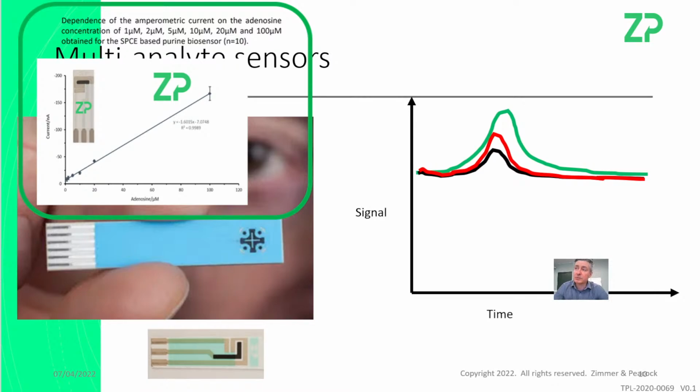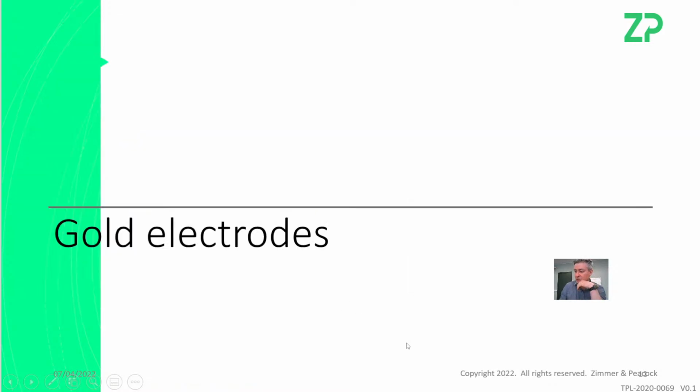The reason it doesn't work well is because you're essentially at least doubling the complexity of your device. You're not only making one biosensor, you're making 2 biosensors, because you have to make the one with, let's say, the enzyme on it, and the one without the enzyme on it. And I've seen people try to do this, and they just double the amount of work they're doing. There are other ways of avoiding backgrounds. I'll talk about mediators later on, but be really careful, because it always sounds like a good idea, but in reality, it's hard to manufacture in high yield and low cost.